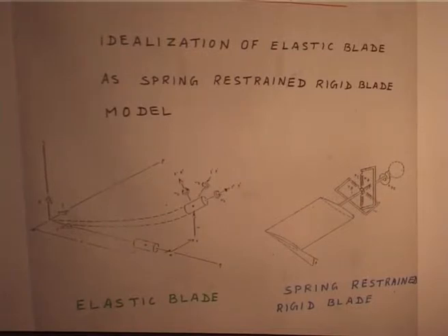Some people may say, okay, I will take 4 flap, 3 lag, 2 torsion and 1 axial. We take 1 axial mode because that has to bring in some effect. Okay. But you look at the frequencies. So, in the rotor blade dynamics group in the helicopter, they analyze, of course, a couple of people whose job is to run every day the natural frequency and mode shape in each mode. Okay. We have developed a code now that is given to HAL.